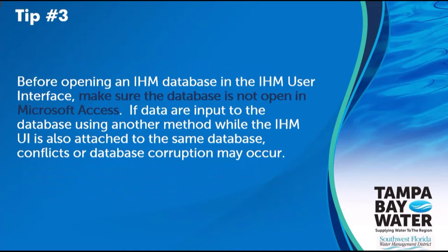Tip number 3. Before opening an IHM database in the user interface, make sure the database is not open in Microsoft Access. If data are input to the database using another method while the IHM user interface is also attached to the same database, conflicts or database corruption may occur.